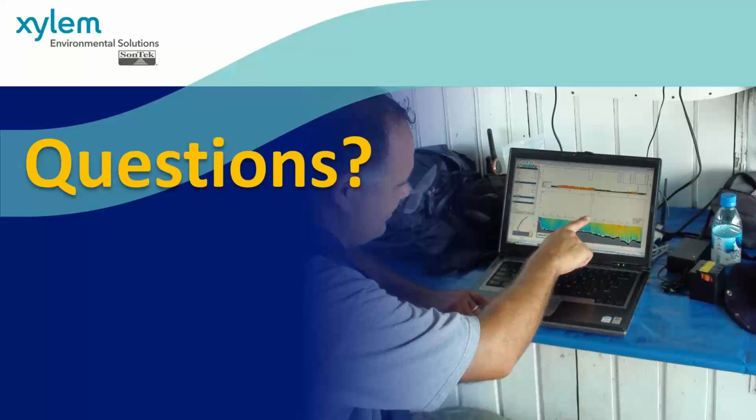So if you have yourself in between the antenna on your laptop and the M9, you might see some issues. Sometimes it's helpful to raise the antenna above the water, so the further you are from the water, the more reliable communication you get.